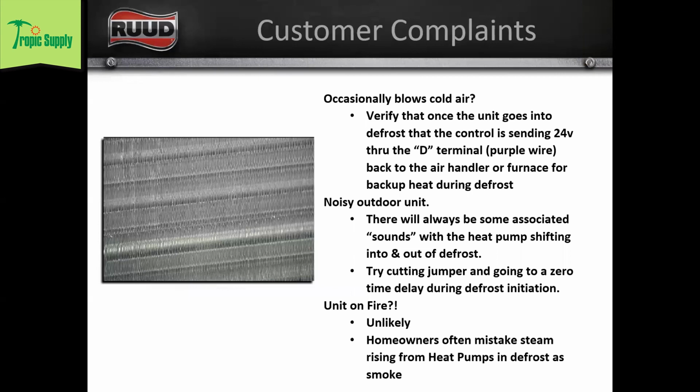That trumpet sound you're talking about, is that when it's going into defrost or coming out of defrost? I've heard it on both, but typically it's during that delay, right? So we de-energize the compressor for 30 seconds, and what's happening is, as the pressures are equalizing during that 30-second sound abatement, the valve is just starting to shift, and then we start back up and build a head of pressure on the other side. I've heard it on both.